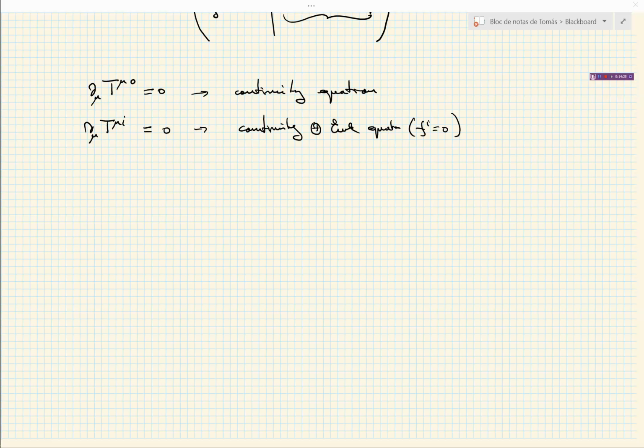And all these modifications take into account effects like viscosity. They can be expressed, for instance, by modifying the Newtonian stress tensor. This is one way of incorporating them. For instance, you can take a look at chapter 2 in the Landau and Lifshitz book on fluid mechanics.